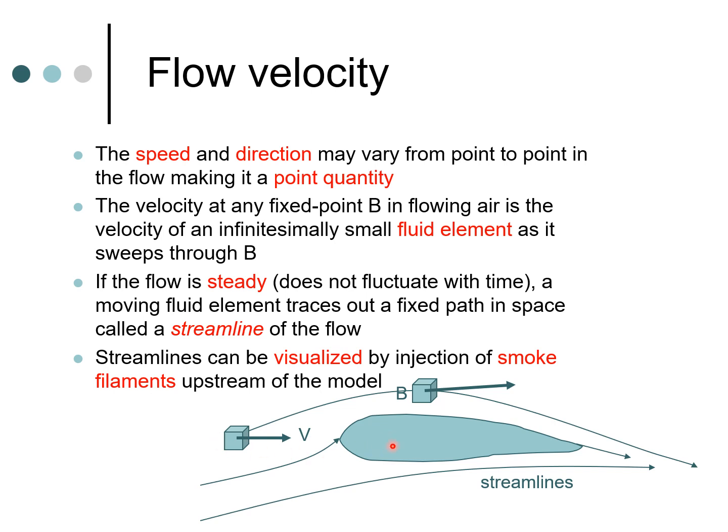So again, we can imagine an airfoil section. The section I have drawn here is a typical airfoil section which is used in wings. If you check out any aircraft wing or helicopter rotor blade, you are going to find the section is something like this. The reason this section is used is because it has very good properties in terms of being able to generate a high degree of lift with relatively low drag.